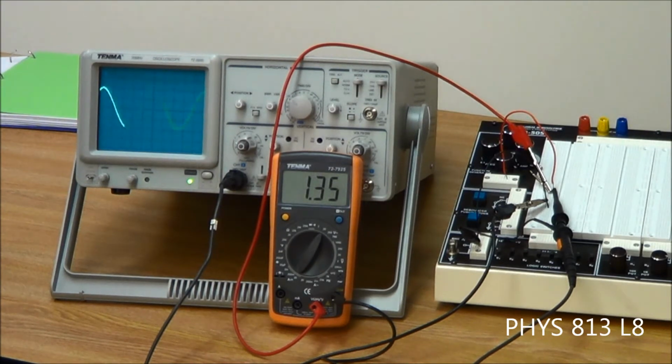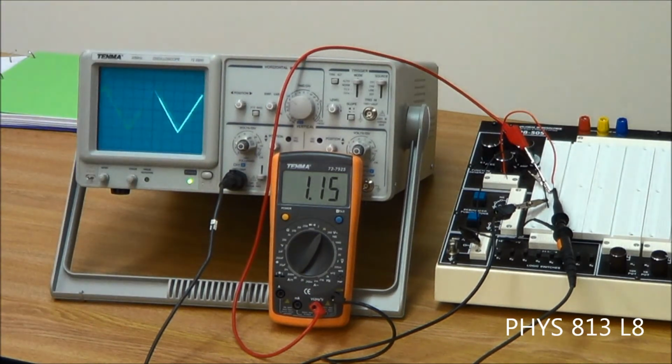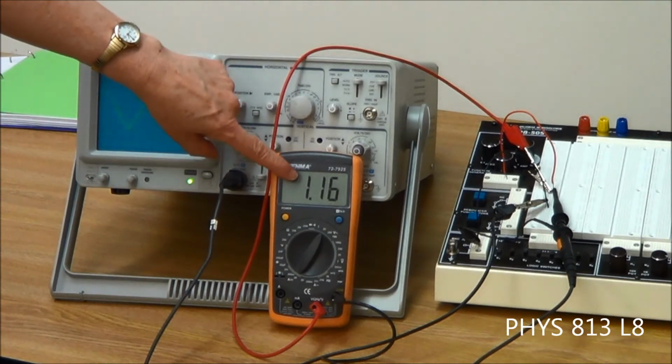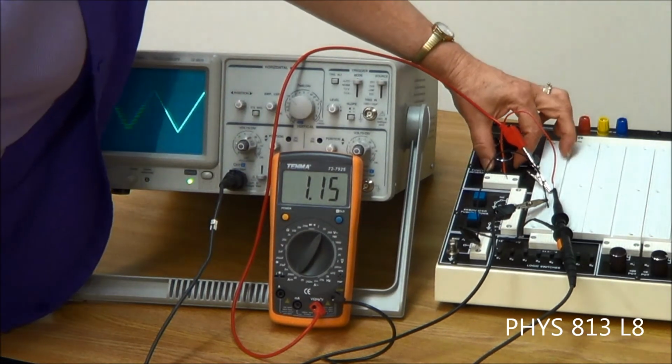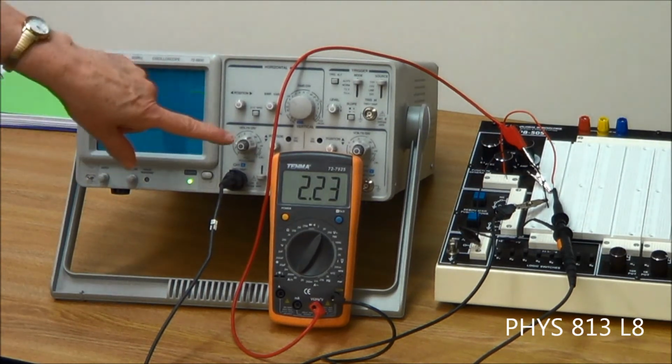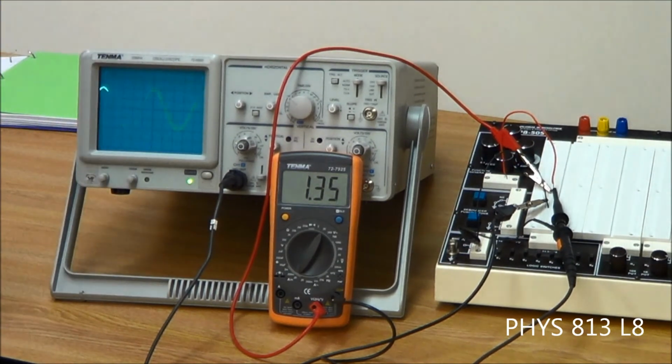Now, what I would recommend is you're going to do the same thing for all 3 waves. So while you have this set at 100 cycles per second, it's very convenient to go over here, change this to the triangular wave, and it looks like the amplitude stays the same. You can make the same measurements, and notice that the voltage here changed. It's not as much when we have the triangular wave as when we had the sine wave. And then we can go over to the square wave, and notice that we're actually a little over 2 volts. So while you have the frequency set, I would go ahead and make all the measurements for the 100 hertz for all 3 waves. And then you can go back and do the second row.